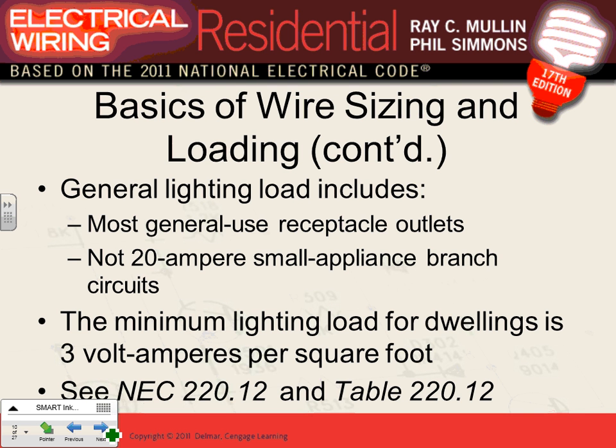Now go back to dwelling. We're doing dwelling. People don't do a whole lot in a dwelling, right? In a dwelling, it's not like the light goes on 8 hours a day. So we treat them slightly differently. For your general lighting and general purpose receptacle, almost always what we use is a 15 amp branch circuit. And we don't use a 20 amp circuit unless you're my brother-in-law that wired all his house with 20 amp circuit. Can I wire the whole house with number 12 with 20 amp circuit?